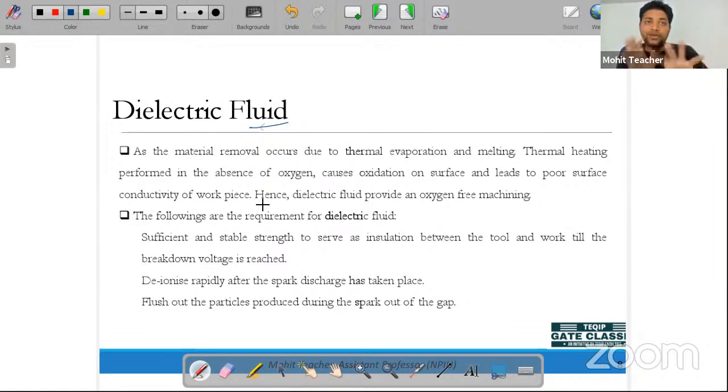If we talk about tungsten inert gas welding, we use an inert gas there, such as argon, neon or helium, or a combination of them. Why are we using that gas? Just to protect the arc from atmospheric gases, especially oxygen. We do not want oxide formation, which is hazardous for human beings and also creates defects in the workpiece material or the welded region.